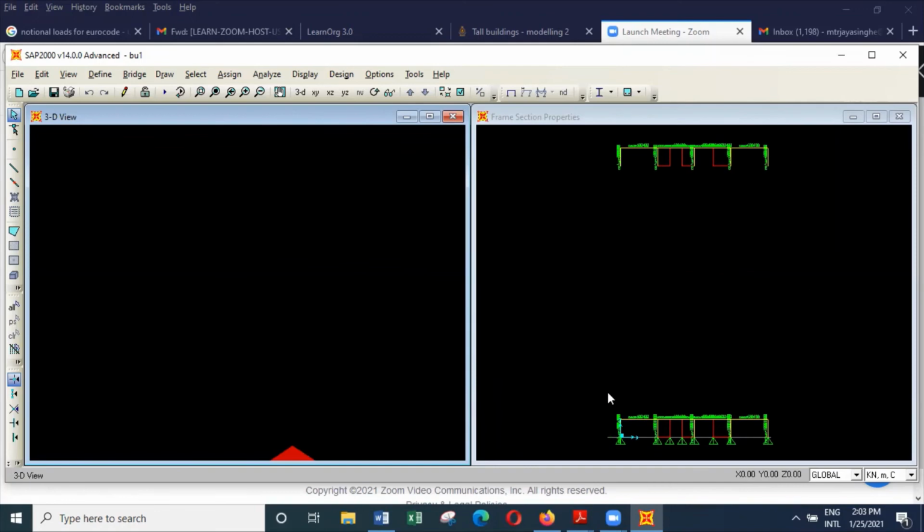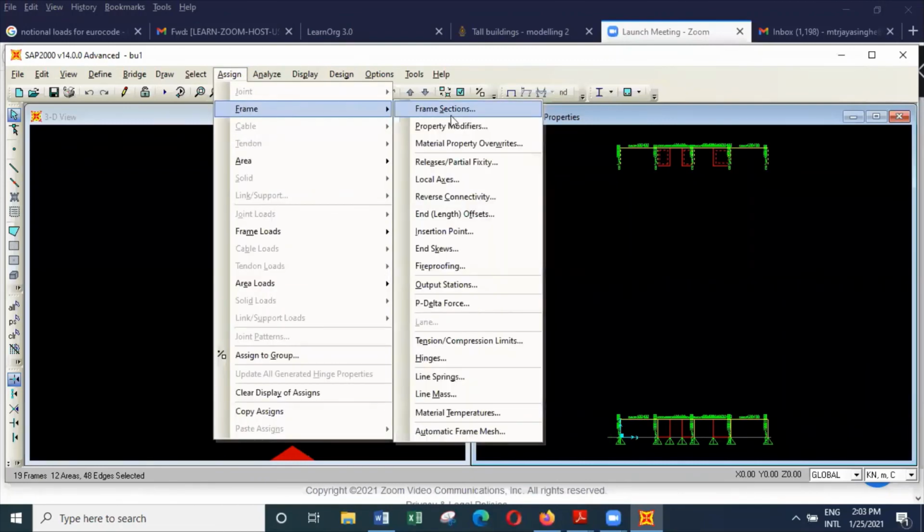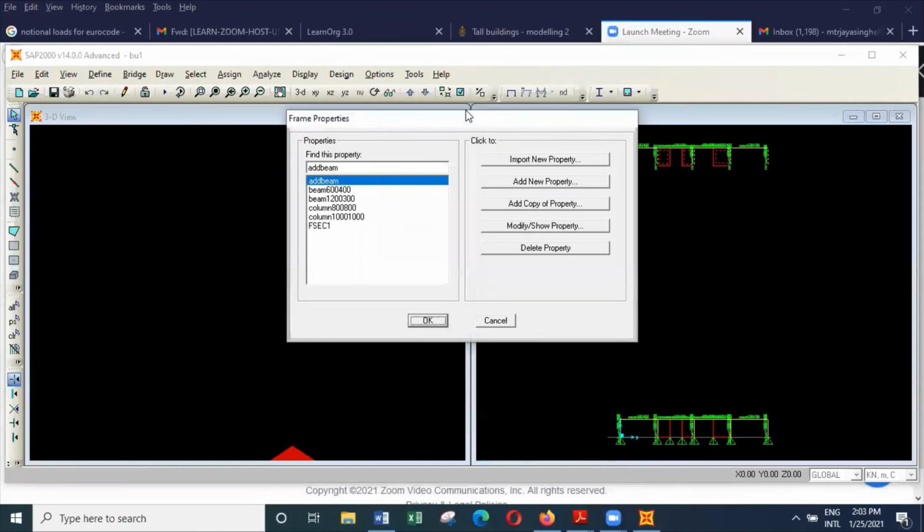In the upper part of the structure, the column loads can be lower. So what you can do is make a copy and replicate this at this particular level. Then you can select all the columns in one stroke. Now all the columns are selected, as well as the shear walls. But when you assign the properties, like column 800 by 800, nothing will happen to the shear walls, because they are not defined as columns.